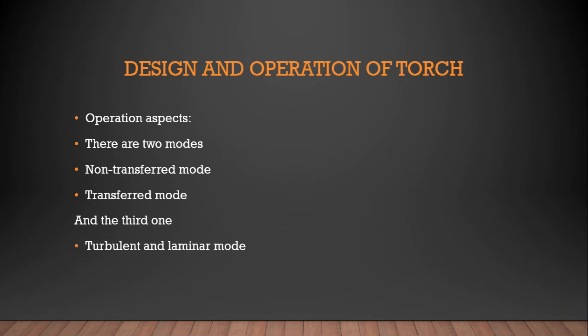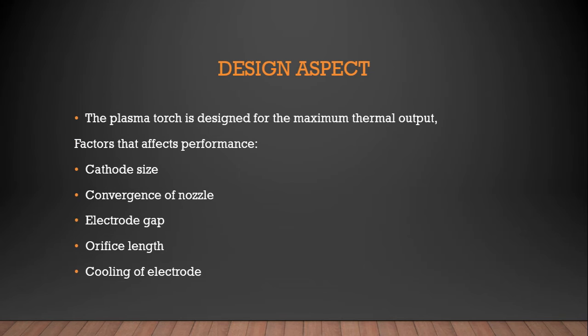For the design aspect, the plasma torch is designed for the maximum thermal output. The factors which affect the performance in design are cathode size, convergence of nozzle, electrode gap, orifice length, and cooling of electrode.